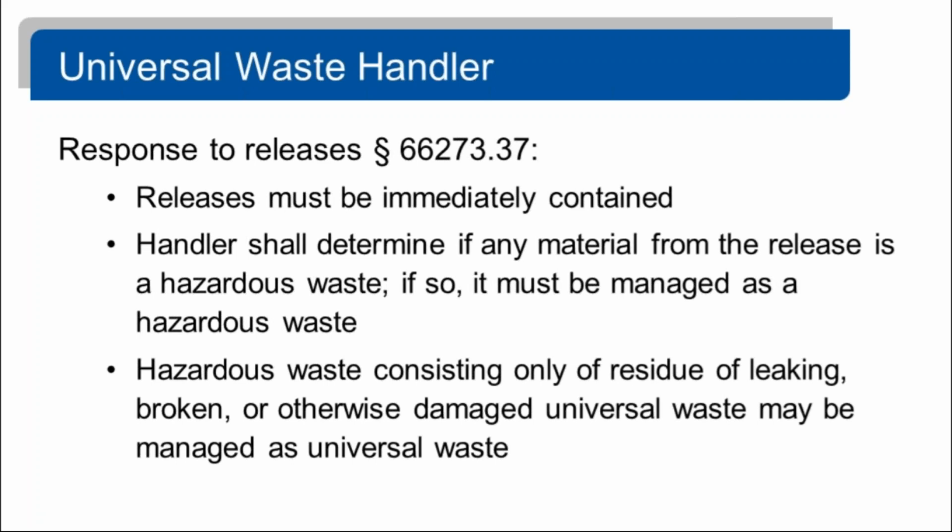Responses to releases. Releases must be immediately contained. The handler shall determine if any of the material from the release is a hazardous waste. If so, it must be managed as hazardous waste. Hazardous waste consisting of residues or leaking, broken, or otherwise damaged universal waste is allowable to be managed as universal waste. And this is the regulation where you'll find it in Title 22, Section 66273.37. And they'll specifically identify in there that you can manage broken or damaged universal waste still as universal waste. It does not necessarily become hazardous waste.